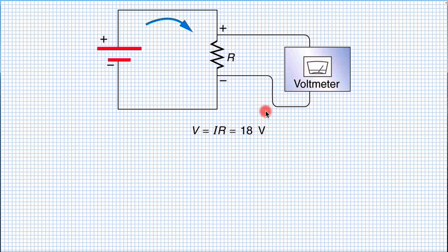So since the resistance can be determined from the gradient of a graph of current versus voltage, we can determine the resistance of an electronic device in a circuit by changing the voltage, measuring the current, and then finding the gradient to work out the size of the resistance.